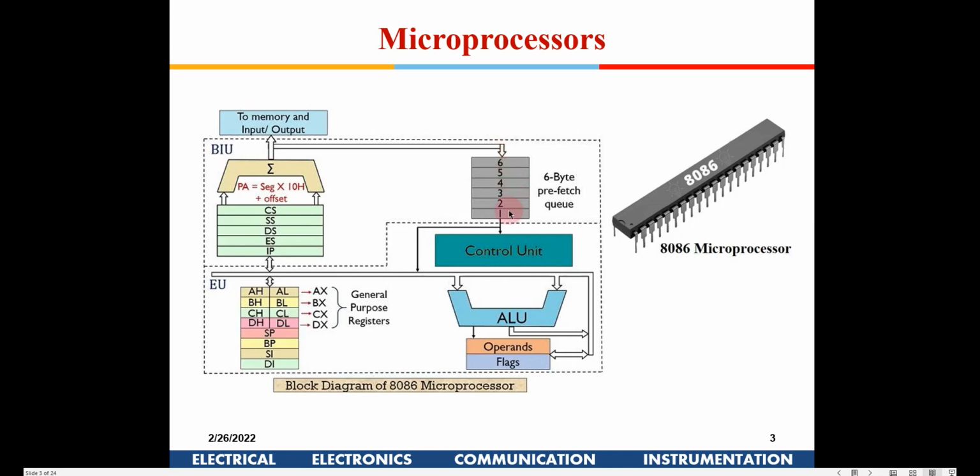Also, when the ALU is doing certain computation, right? So what the control unit does, to save time, is also known as a kind of pipelining. To save time, the next instructions are brought, prefetched and kept here, and also decoded. We'll see why there is a requirement for a decoder also. Why is it that the instruction requires to be decoded?